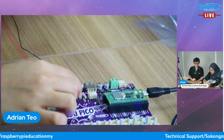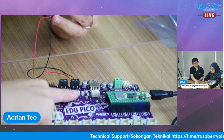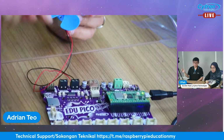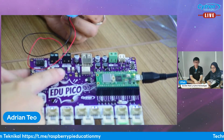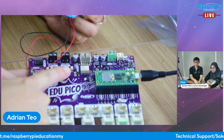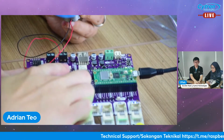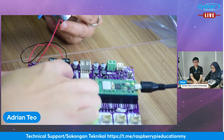Right. So to test, what Ifa did is she tested the motor directly by pressing the button on top of it. You see these 4 buttons here? These are for 2 directions, front and back. By pressing this button, you can test the motor immediately. No need to do coding yet.